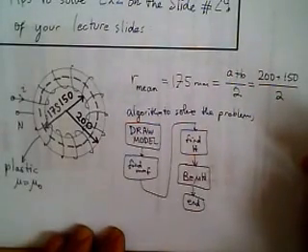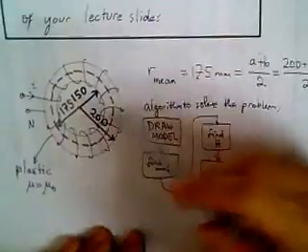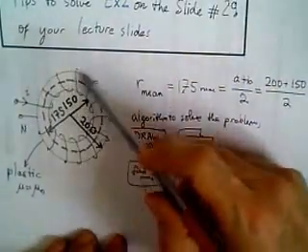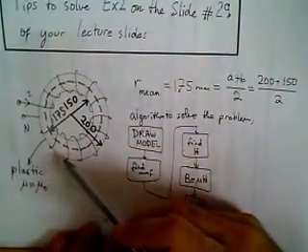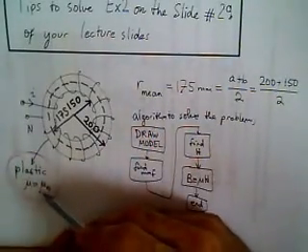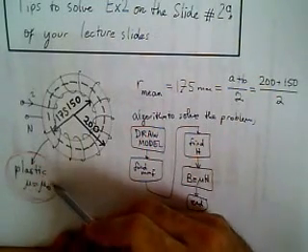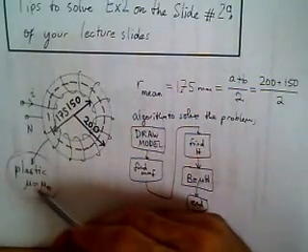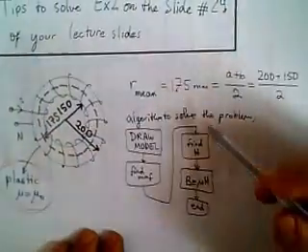In another example, given in number 29 of the slides of your lectures, we have a toroidal core material and a loosely wound coil throughout the material, and this material is given to be a plastic. Although it's not mentioned in the question, plastic is neither ferromagnetic nor ferrimagnetic, so we may assume that, although in real life it's not exactly so, its permeability equals the free space permeability. So this is the same as an air core material.